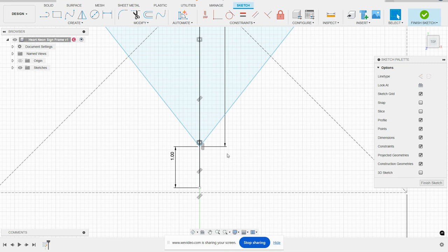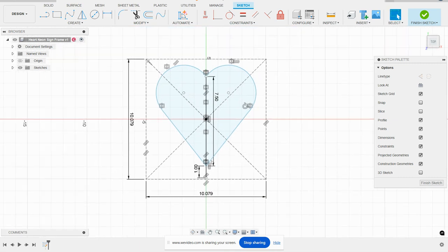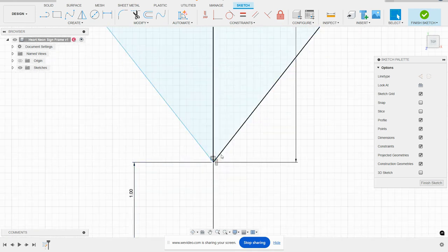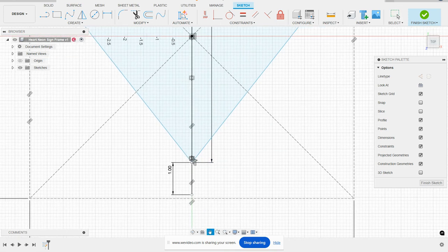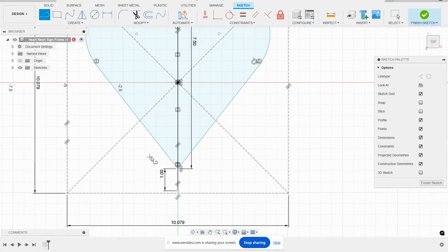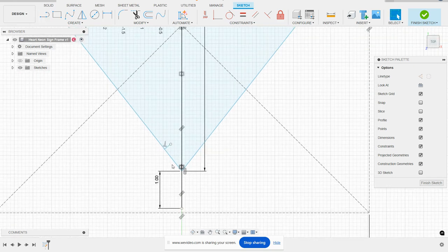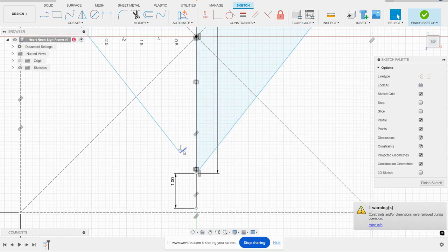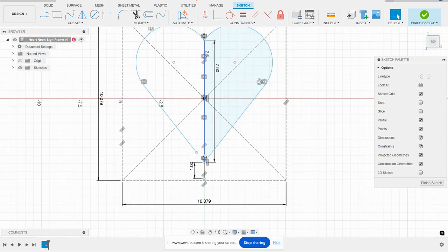I'm looking pretty good. Now, the thing is, with our frame, okay, the LED strip is going to have to snap in here, and it's going to continue around, come all the way around to the very end, okay? That means we cannot have a true connection, okay, in this intersection right here. So what I'm going to do is come up here, just simply grab a line, and come in here and just draw a line out, just like so. And now I can use trim, and I can trim that out, and we can also get rid of this line because I do want there to be a gap between these two.